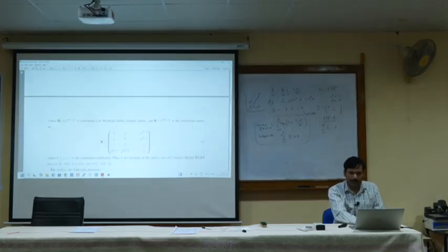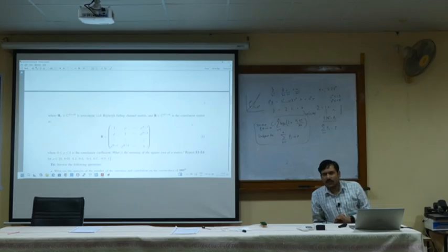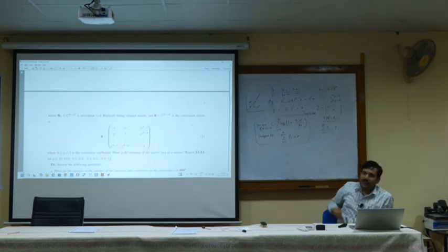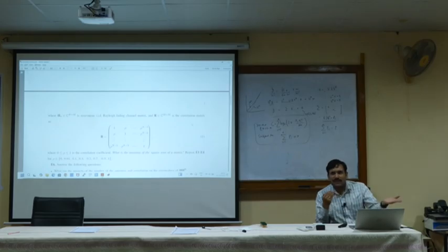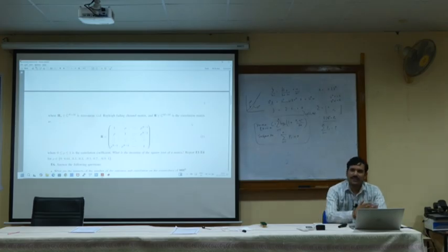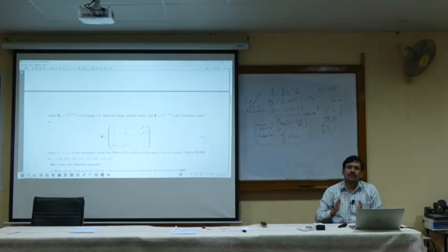After you have generated the correlated channel, we can apply the water filling algorithm and equal power allocation to see what happens to the rates. In the slides by the professor, you have seen that correlation reduces the rates. Why does correlation reduce the rates? Because of the condition number. Condition number and rank are the most important things for a channel. If the rank of a channel is less, we cannot transmit more data streams than the rank.